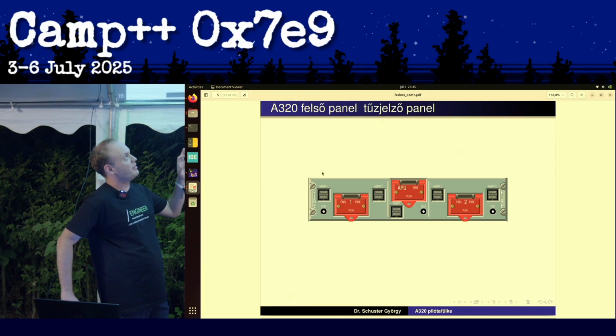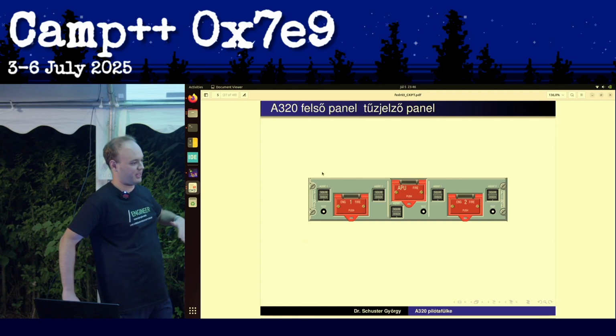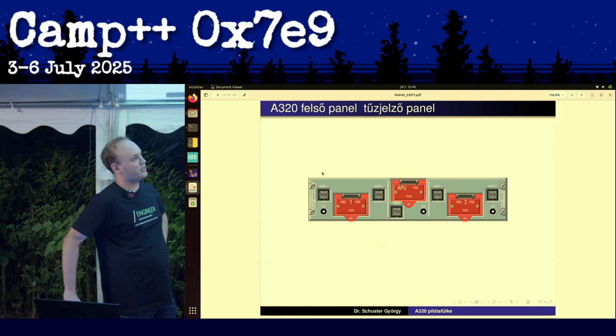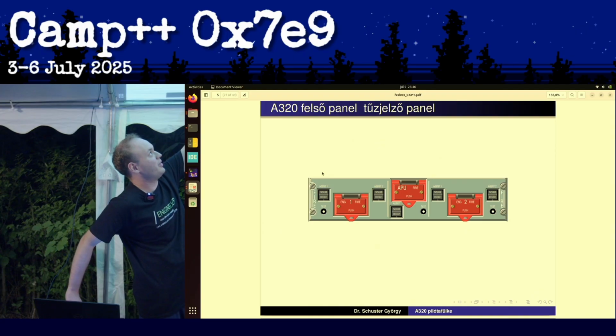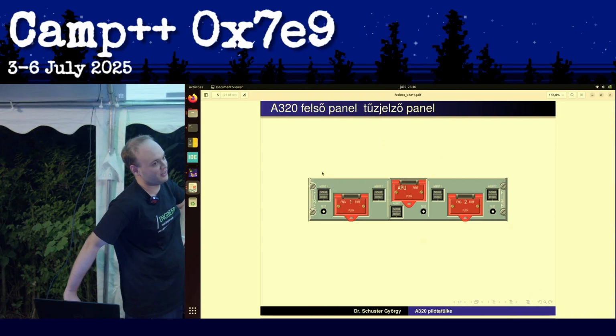But basically, when you press one of these buttons behind the covers, it disconnects all fuel, hydraulic, and electronic supply from the engine entirely, to keep it safe. You also have the option to discharge two separate fire extinguishing agents into the engine with each of those buttons.